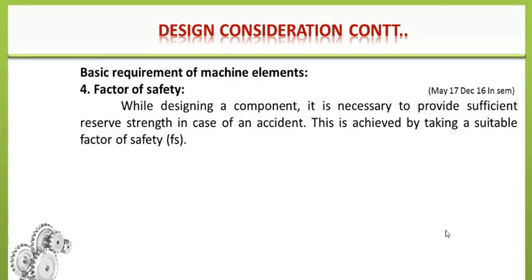Then whatever stress is calculated by the designer is not the actual stress during actual working condition. Somewhat more stress is present during actual working condition, but that stress we don't know. So if we consider the stress calculated by the designer as the maximum stress, then in actual working condition the component may fail. So what we need to do in this case is increase the amount of stress somewhat.